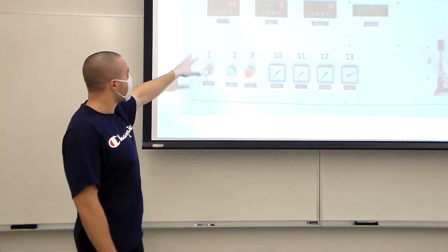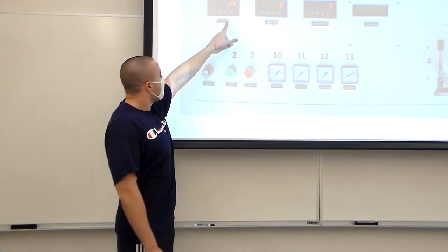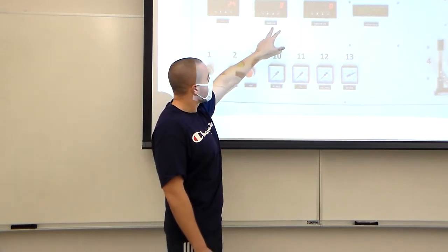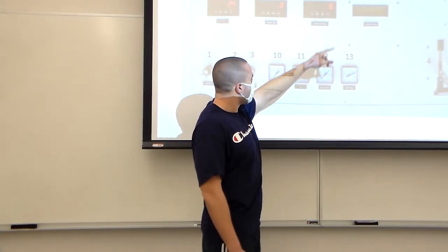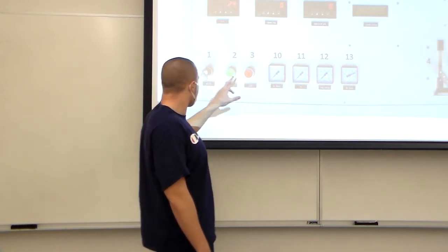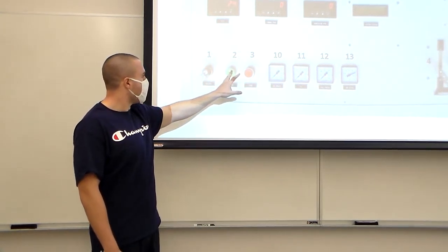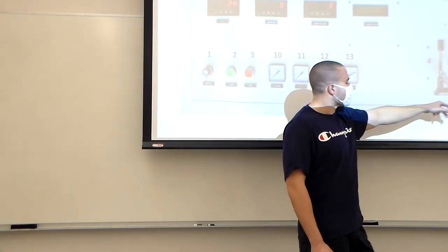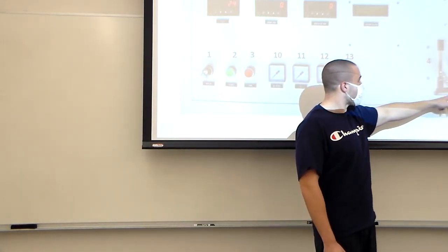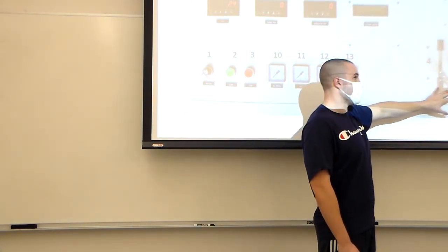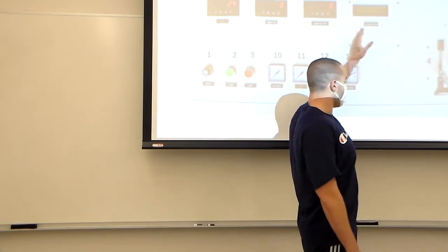This right here is the control panel. So this is the TIT, the turbine inlet temperature. This is the engine RPM, the generator RPM. These are some dials that I don't exactly remember what they are. This is the master key, the go button, the stop button. And then these are your 2 primary levers that you're going to use the whole time. This right here is the throttle lever, which affects the engine RPM, the turbine RPM directly.